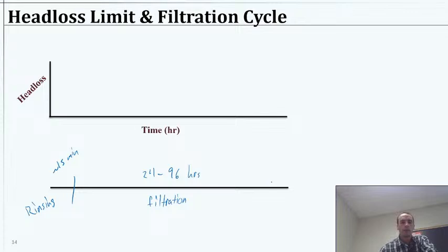And then after that, we would have some sort of backwashing. And we might have a couple steps here. We might have maybe an air injection and then a regular backwash. Really, we could call both of those steps the backwash period, but the difference would be we're not using water during the air purge, so we're not sending that water to waste or consuming water that we've already produced. So that's why we might distinguish it. And in total, this would also be something like 15, 20 minutes.